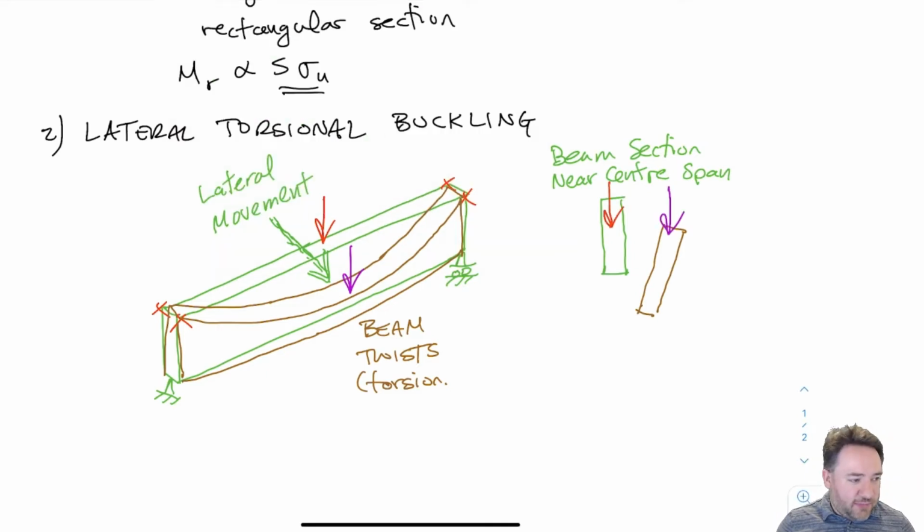So there's my best artist's rendition of a beam twisting and lateral torsional buckling. And so you can see that the bottom of the beam over here twists sideways a bit, but really predominantly it's the top of the beam that's going over.